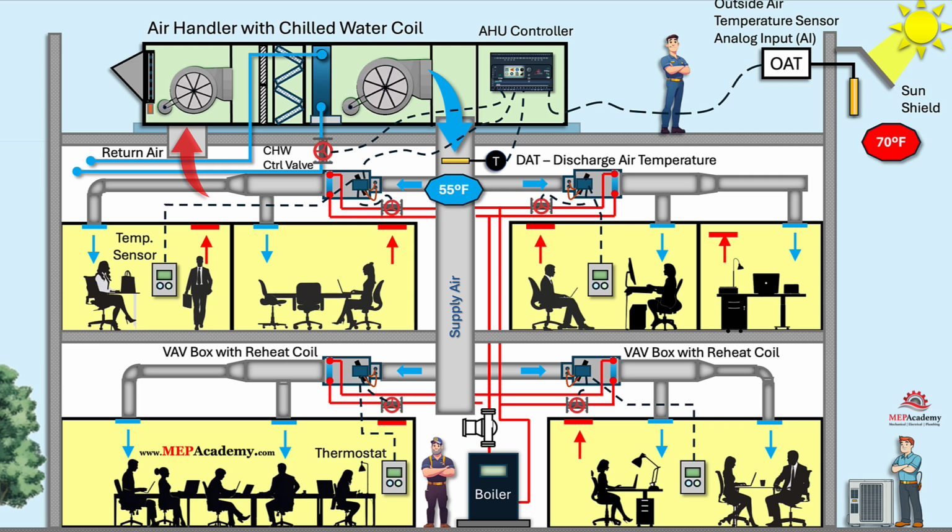To prevent the supply air temperature reset strategy from compromising dehumidification and to ensure the required relative humidity levels are maintained, several control strategies and hardware devices are typically employed. A humidistat, or humidity sensor, can be integrated into the control strategy. If the indoor RH exceeds a set threshold, typically around 60%, the system can override the SAT reset and maintain a lower SAT, ensuring that sufficient dehumidification occurs to maintain comfort and meet code requirements.